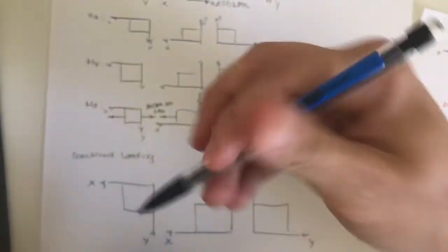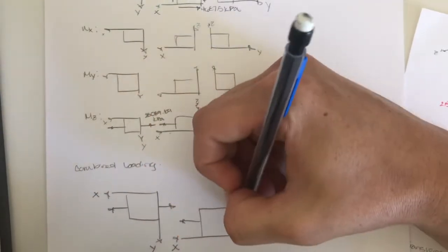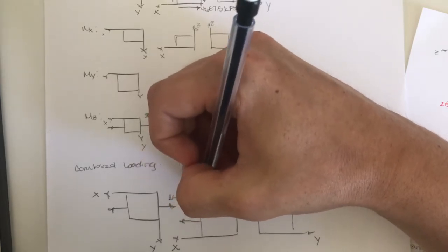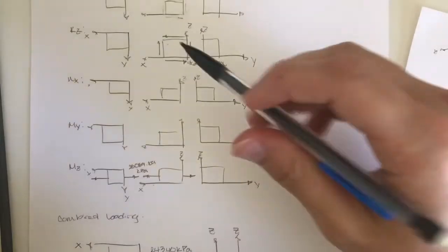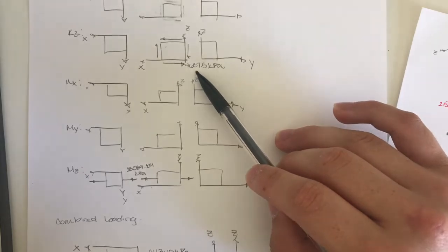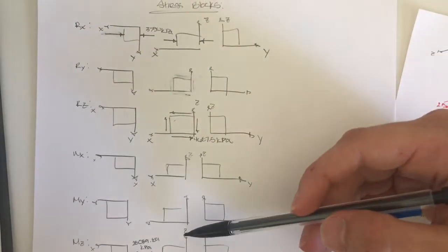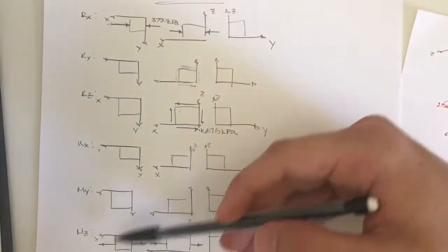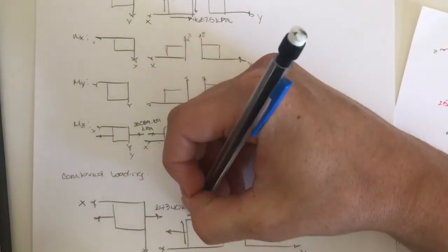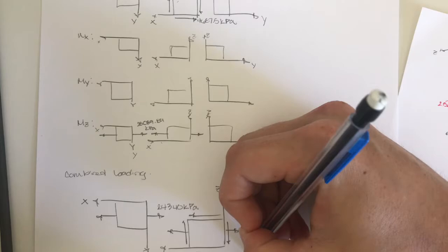So that gives a tensile stress in the X direction of 24,340 kilopascals. And since in the reaction in the Z we have a shear stress of this value right here, there is no other shear stress value in this plane, the XZ or the XY or the ZY. So that will go uninterrupted and will remain the same value, 4687.5 kilopascals.